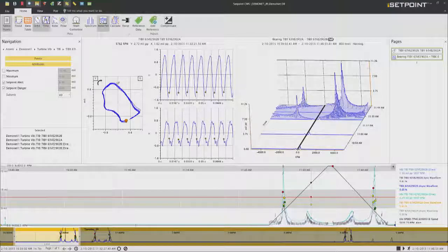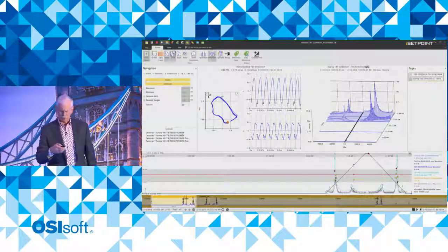It runs through a resonance and a second critical speed. So my machine is changing, and it's very interesting. The speed is changing, the vibration amplitude is changing, the vibration frequencies are changing. And so the system recognizes that, and all these little tick marks that you see are waveforms. So the system is basically storing waveforms because it needs that data to characterize what's happening in the machine.